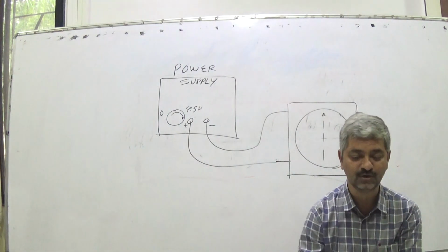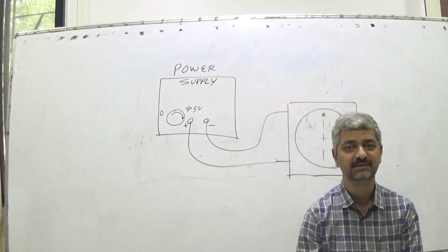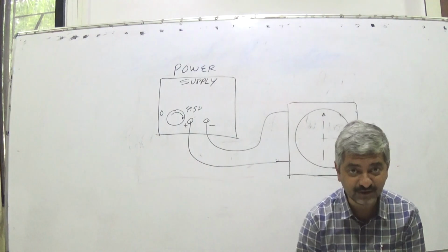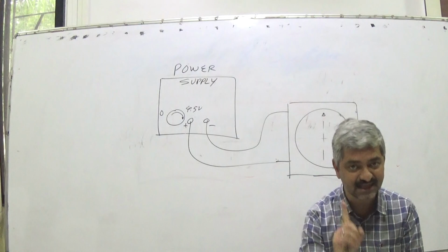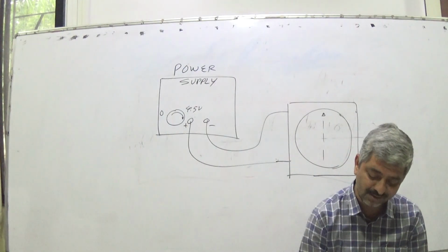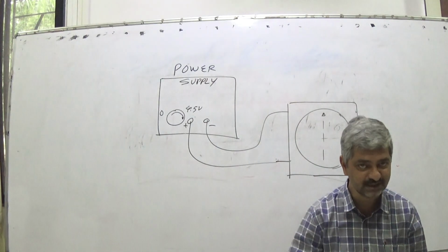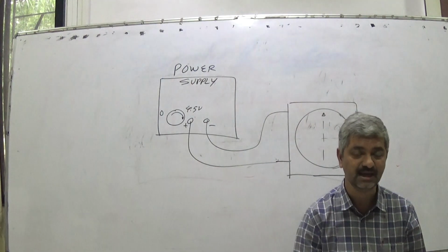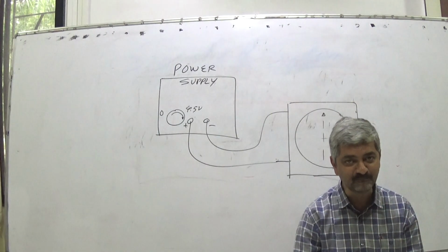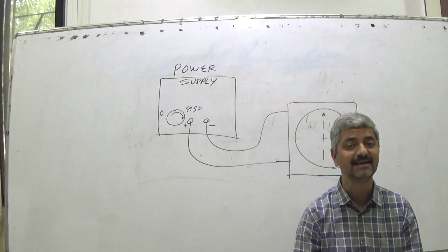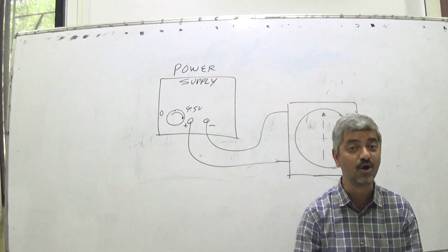So, because of the physical element of that spring, the weight of the pointer, or that actual pointer, it's negligible, but it is there. So, because of the overall physical arrangement, what is going to happen is that there will be a maximum rate at which the system can respond.